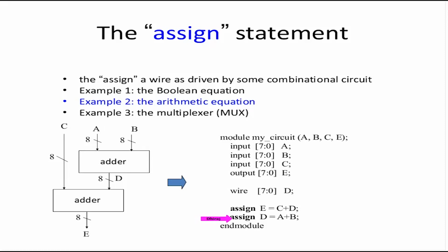This is different from a regular software language, in that both these assign statements are parallel to each other, in the sense that the synthesis tool will understand that first D has to be computed, and the D will go as an input to this adder.